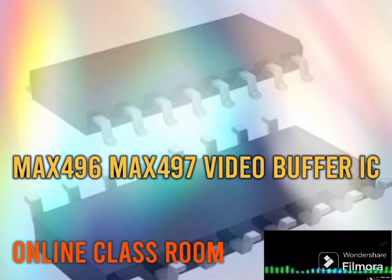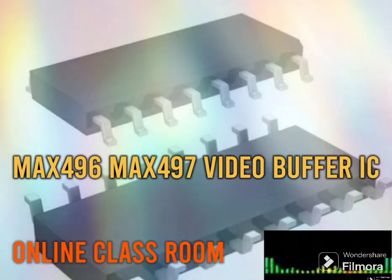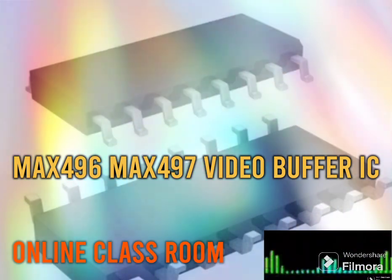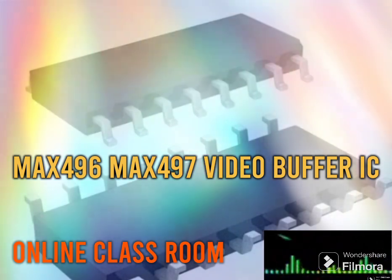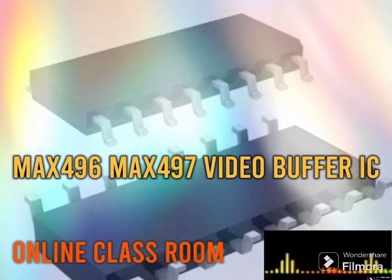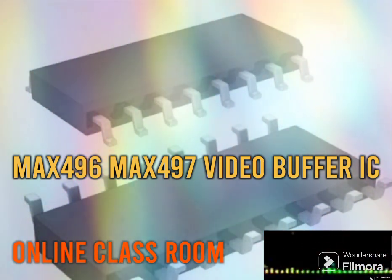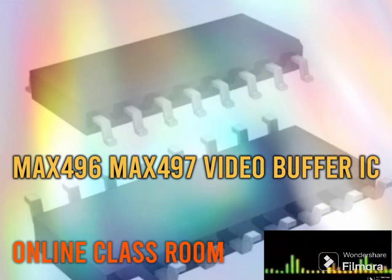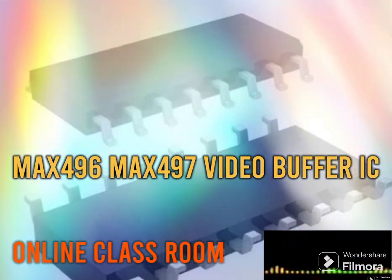The max496 and max497 are video amplifiers that have 4 channels and operate at high speeds. They have fixed gain settings of plus 1 and plus 2 respectively. These amplifiers use a unique two-stage voltage feedback architecture that combines the advantages of conventional voltage feedback and current mode feedback topologies. They have wide bandwidths and high slew rates while maintaining precision.